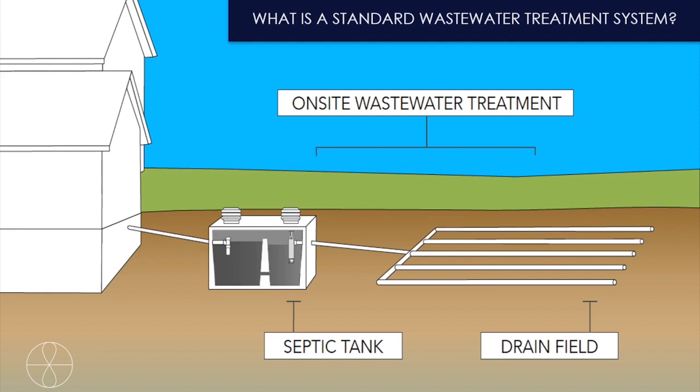It flows into a series of perforated pipes in a standard system where it percolates into the soil. The reason the pipes are laid out this way, relatively wide and shallow, high in the soil profile, is because it's actually the soil below the pipes and the stone that does the treatment. The soil does the treatment, but the soil can only do the treatment if the soil is unsaturated, meaning the only moisture getting into that soil comes from the pipes.